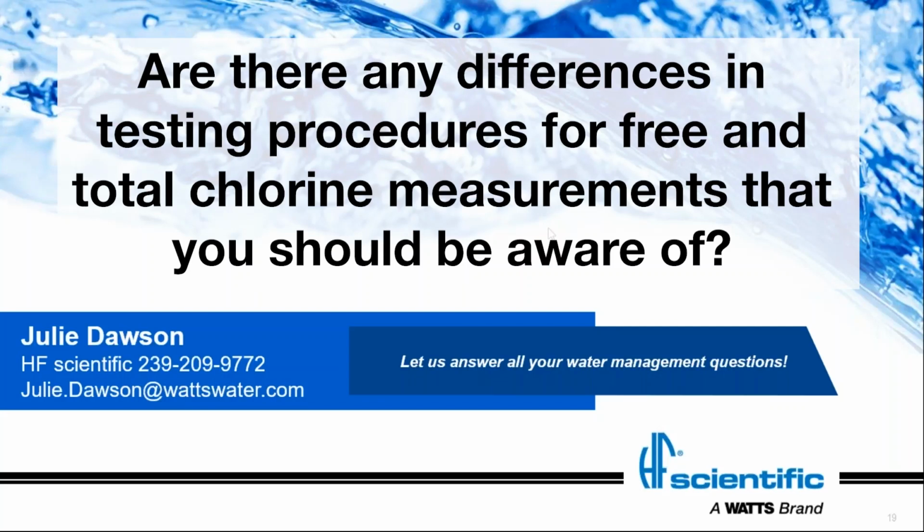So we want to let it go its full reaction time. But we want to make sure that we measure that free chlorine within that reaction time, or if there is excess DPD in the sample, then it will start to react and you will recognize some of the total chlorine instead of the free chlorine.